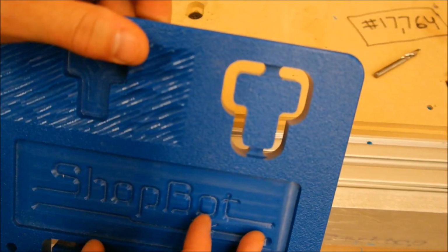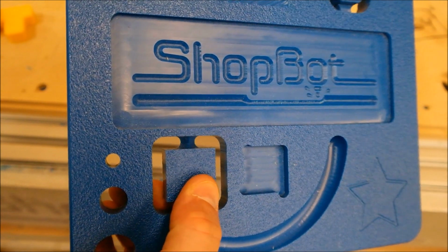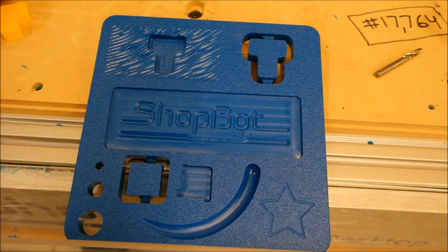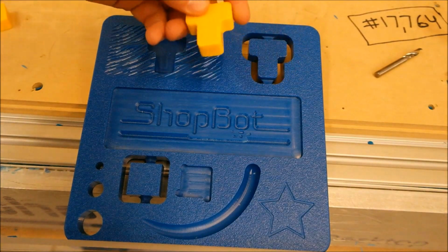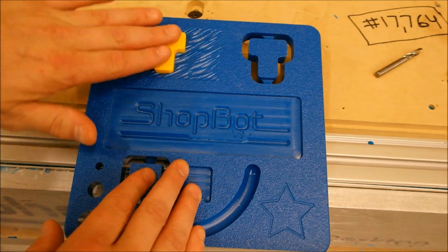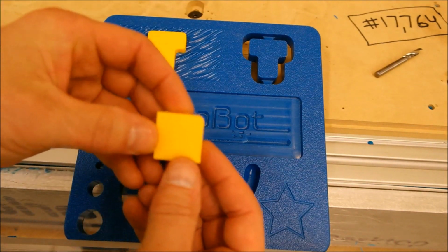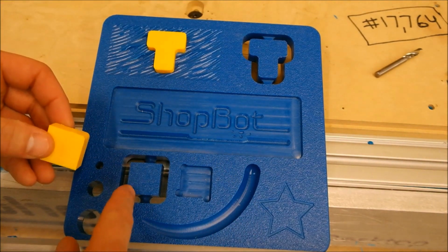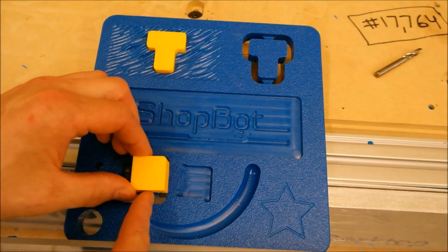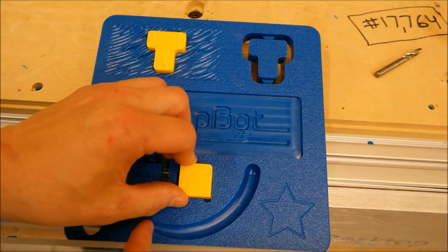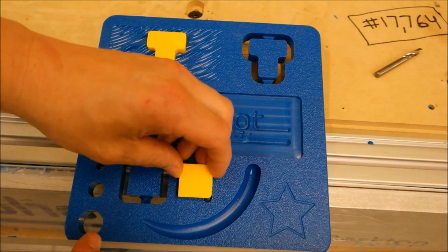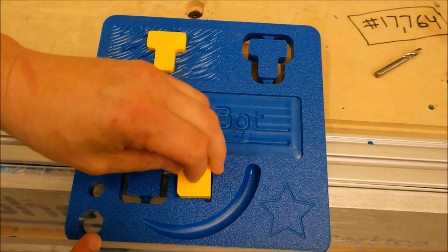So let's pause and actually look at these inserts here real quick. So there's the ones we just cut with the dog bone, and there's our inlays from up above. So if I clean off the tabs with the sander, I did them out of yellow so it shows up a little better on the video. There's that tolerance up there. It fits in and out nicely. And then down here you can see adding the dog bone or the T-bone to the pocket. I made a point of leaving the one corner round so it only fits in there one way. But those square corners now fit because of the dog bone and the T-bone.